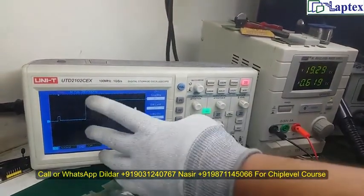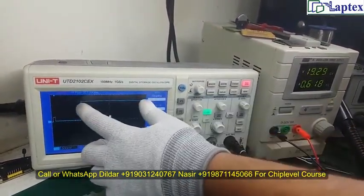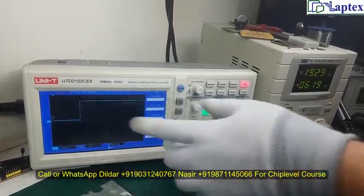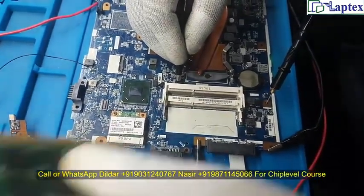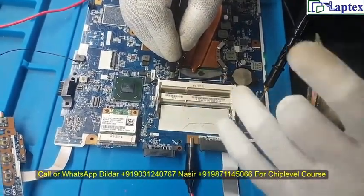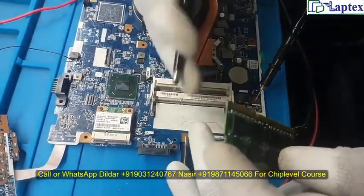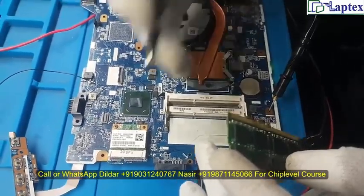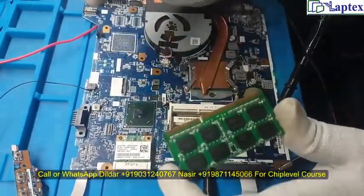As I have adjusted it to the last limit, now no reset is taking place, because reset will be executed when it gets the RAM card on the board. There is a RAM card missing in the slot, so the CPU is unable to find the reset signal. So it is not resetting anything because it is not getting any RAM module in the motherboard.